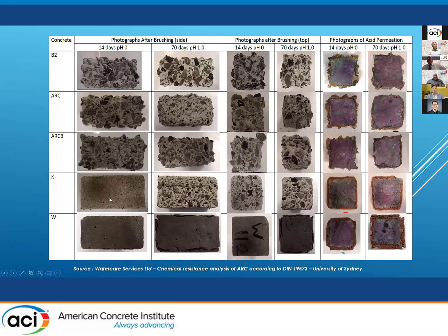K, this is a calcium aluminate-based cement, and so these are materials that are performing well, and this is a geopolymer concrete, and this is an ambient cure slag fly ash system. And so it was really sort of chalk and cheese between the exposure of Portland cement-based systems versus the calcium aluminate and geopolymer in that particular test procedure, but it certainly has its limitations.